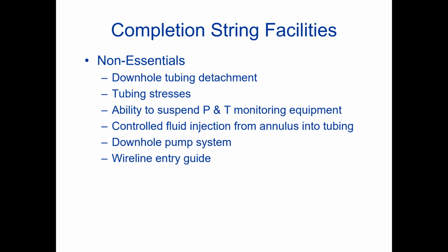And because the tubing is fixed at two points, at the wellhead and the packer, that can damage the tube. So we have telescope-like devices where the pipe moves inside the sleeve and takes care of the stresses.